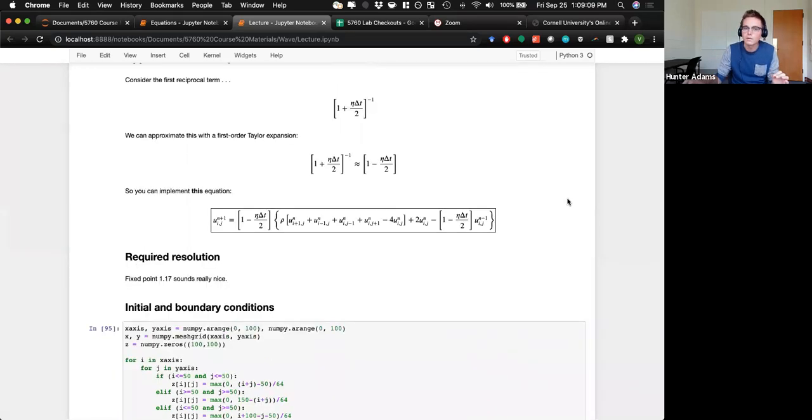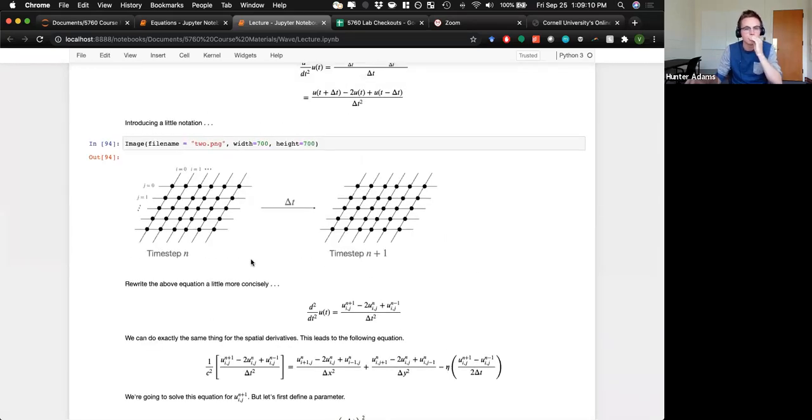What you should be thinking about is building a state machine that perhaps spends those 1,000 cycles walking through a tile of nodes. So suppose, for example, we're thinking about this tile of nodes shown on the screen. Maybe the hardware that you parallelize is logic that systematically walks through these nodes, paying attention to the interfaces here, but updates each one, as many as it can in 1,000 cycles, and then you make many, many copies of that tile in order to build as many nodes as you possibly can.